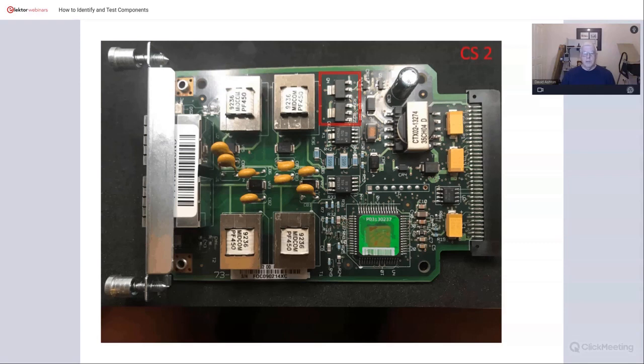That's slide 2. These things here are SOT-223 outline transistors. SOT-223 is the package name. The name on these is FZT705, and on the back side there are two more called FZT605. They're actually Darlington transistors. They've got fairly good ratings, 120 volts, 4 amps. So pretty useful little transistors there.